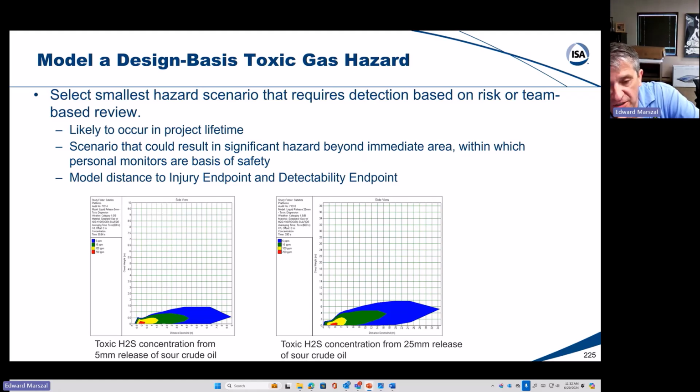For fire detection, moving a fire detector 1 meter could be catastrophic, depending on where you moved it. You can move it in front of a piece of equipment. Gas detection is a little bit more forgiving because as the equipment moves around, any gas release is going to engulf and go around pieces of equipment. So it'll kind of disturb the profile of the gas release, but not break it entirely.